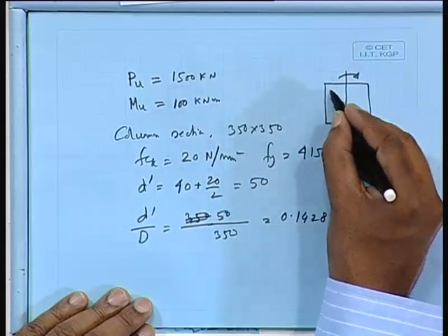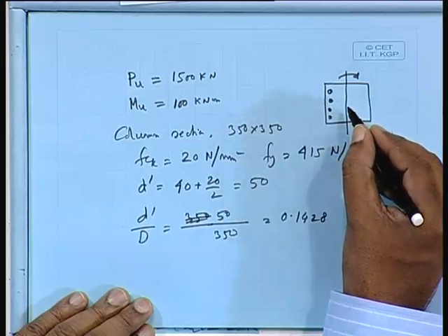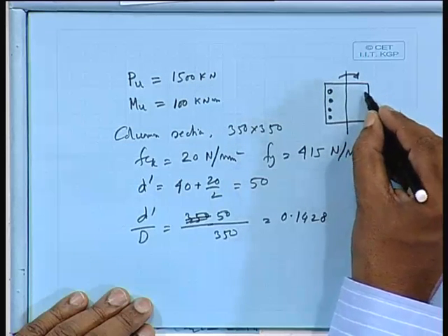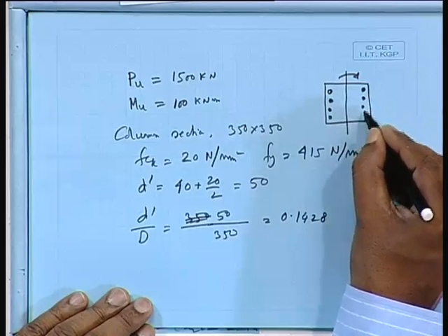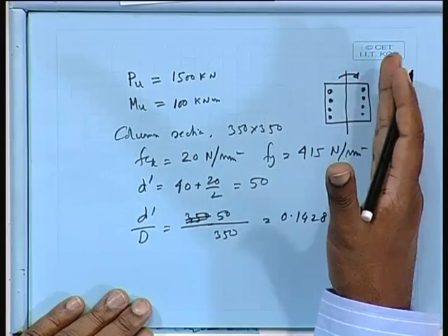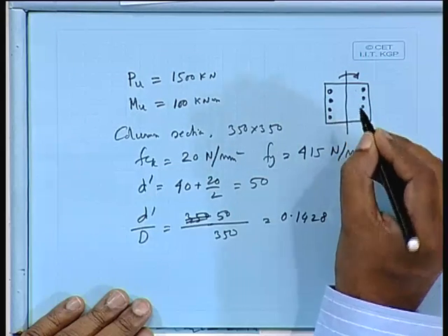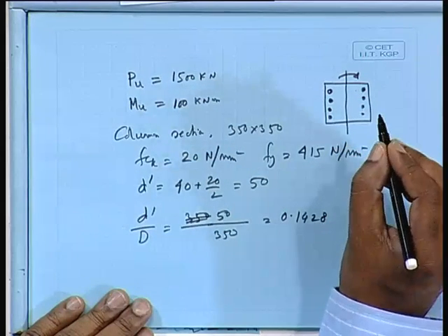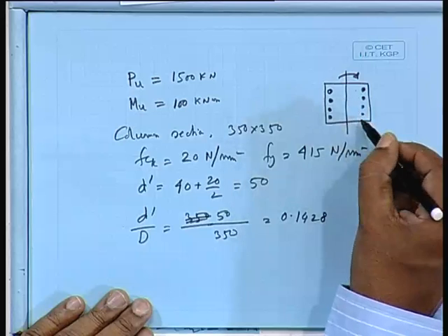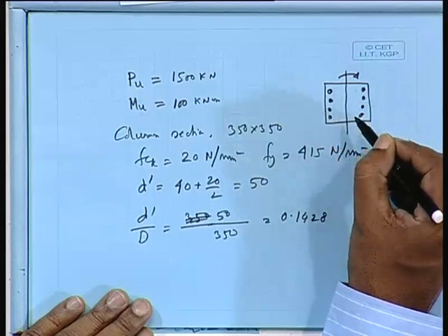We have to provide the reinforcement along this, then only we shall get the maximum benefit, because it will be as far away from the neutral axis as possible. So, instead of providing it here, we provide like this for uniaxial bending. We are talking about uniaxial bending. That means the bars can be provided along these two lines. Is it clear?